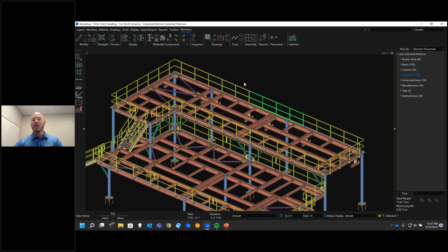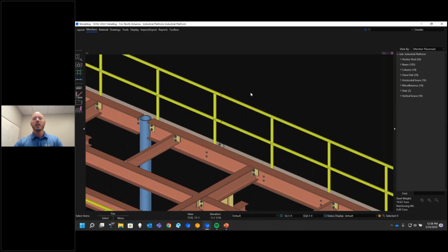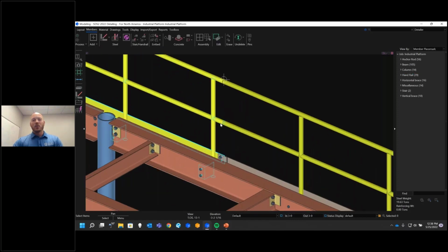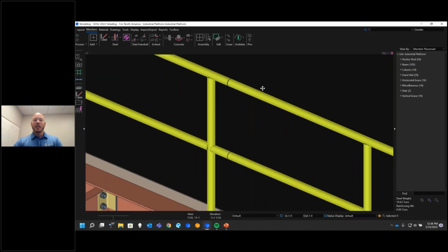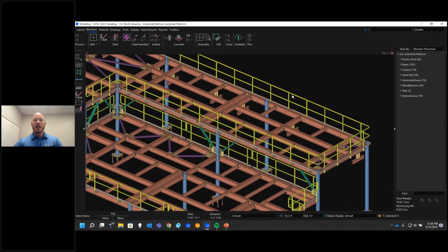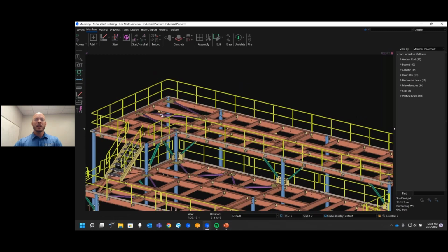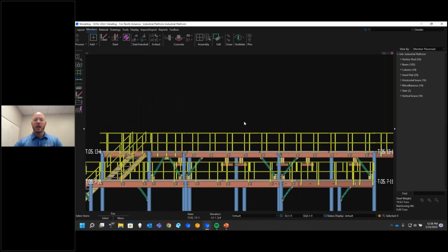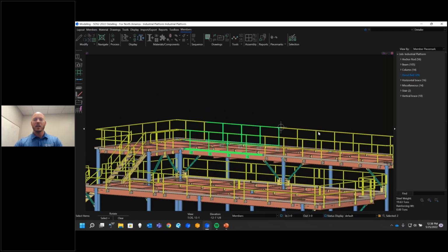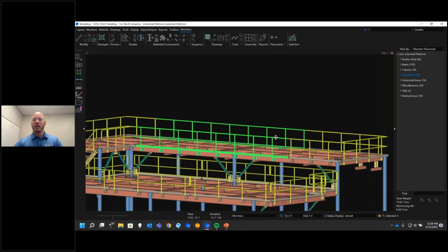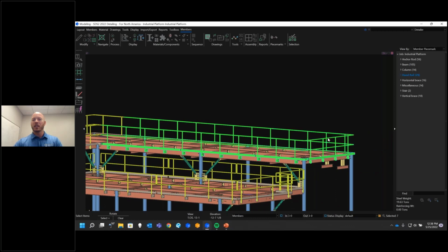And then you can see it's not one rail all the way along here. We did split this up into individual rails. Right now, the way this works, we always do a welded splice with the layout tool. I don't necessarily want that, so I'm going to delete this and show you a different way of laying these out.